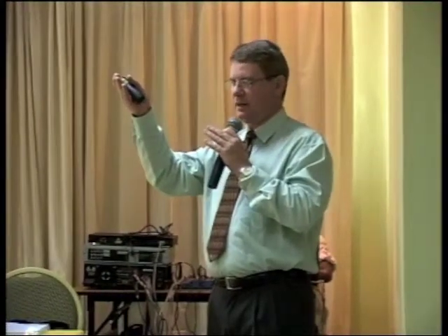Some decisions sometimes are made this way. Okay, I know the cable was mechanically affected. I know the fiber didn't break. I know that attenuation goes back to the normal level. Then I will leave the cable this way. If some fiber breaks, in the future I will take some action to correct this.